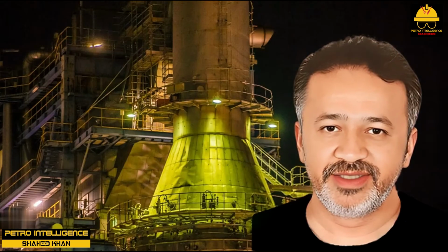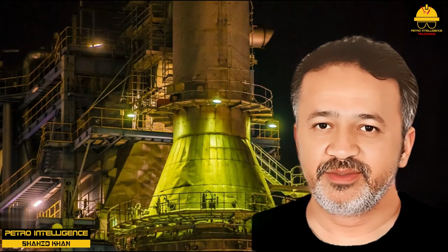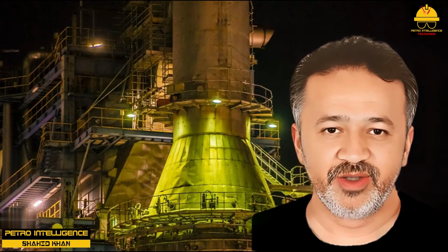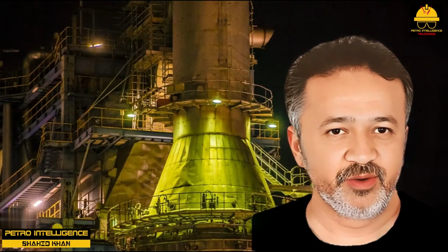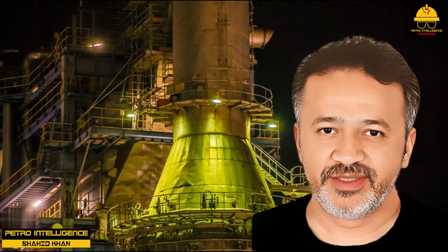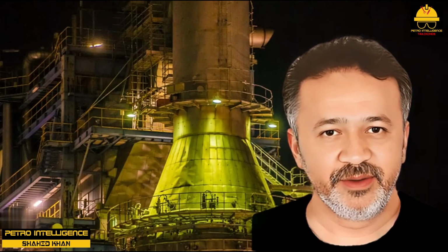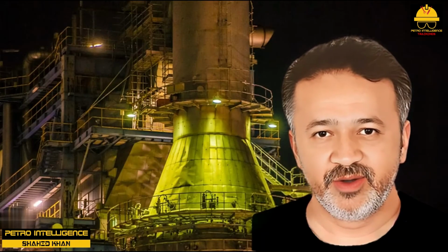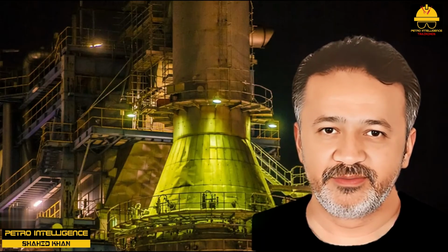The cane was crushed by electric motor-driven rollers to recover the sweet juice. The juice was then boiled down and partially evaporated, using the crushed cane as fuel. I noted that the top of the boiler chimney was about 1/3 of the diameter at the base of the chimney. The reason for this large reduction in chimney diameter is to help induce a draft by increasing velocity of the flue gas in the upper portions of the chimney.